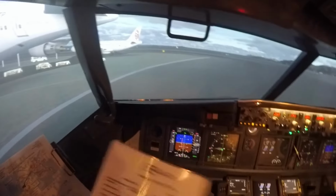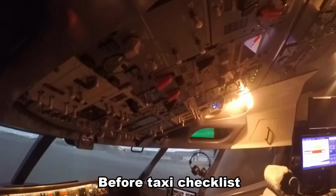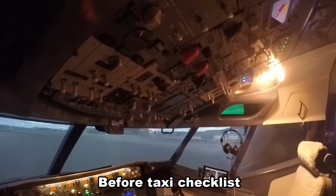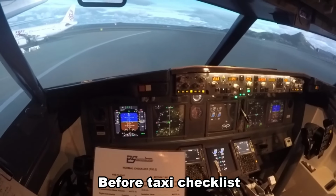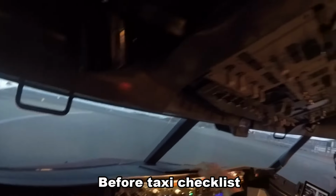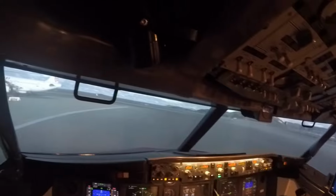Alright, so before taxi checklist, generators are on, probe heat on, anti-ice off, isolation valve auto, engine start switches continuous, recalls checked, auto brake is RTO, engine start levers idle detent, flight controls checked, ground equipment is clear. Before taxi checklist complete. Alright, so taxi and runway turnoff lights are on. Now we'll just taxi to runway 25 right.